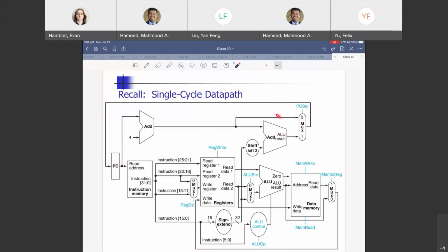And you also have this separate circuit here for the branch address calculation. So shift left by 2, add PC plus 4, and go through a mux. Now, Zach asked a question on Piazza, I think, about PC plus 4. Why PC plus 4? Why not PC? So you see the calculation is PC plus 4 plus branch address, right? Think of it in terms of a loop, right? Satisfies, doesn't satisfy.